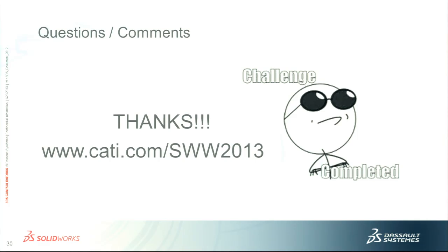Development in SolidWorks, do you consider that a part, or just an assembly? When we work with weldments, we do multi-body part files. So are you talking about creating a cut list? And it's a part because it's welded together, you can't take it apart. Right. Yes, no. In a bill of materials, one part number. And then you can create a document to show how the pieces get welded together. Right, but it wouldn't be considered an assembly with a bunch of parts, right?